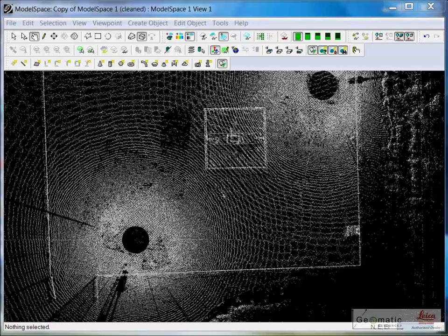Using Cyclone to create an animation, there are several techniques, several different methods you can use, different ways to set everything up. What I like to do is determine the route I want to take through the site, how I want things to be oriented, and then place my cameras as I go.